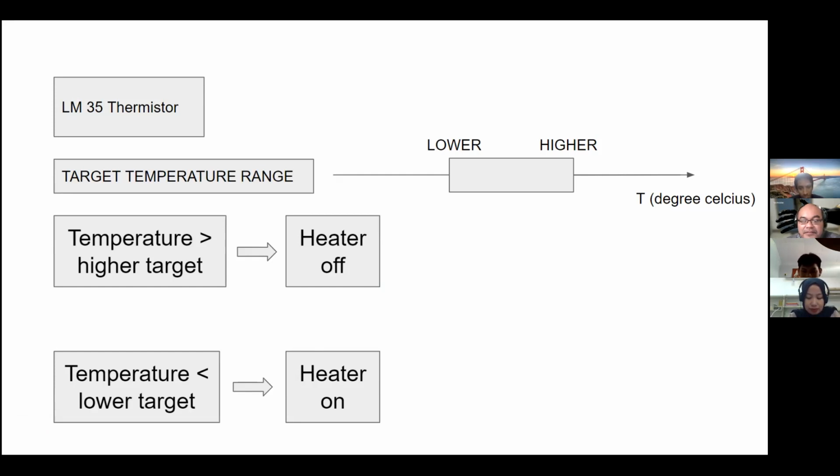That's why I use a heater, sir. Still, if you use a heater, your design is not active temperature sensing. It is still passive, right? Right. And what we want you to make is active temperature sensing. Do you know what to change? We don't use the thermistor, and we directly control the current going into the heater. Yeah, you are smart, you understand.